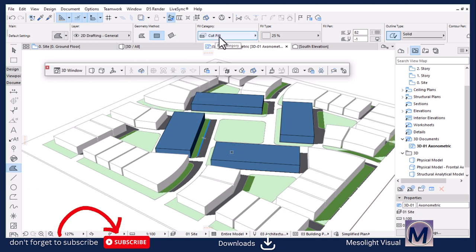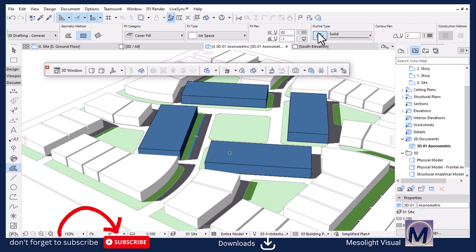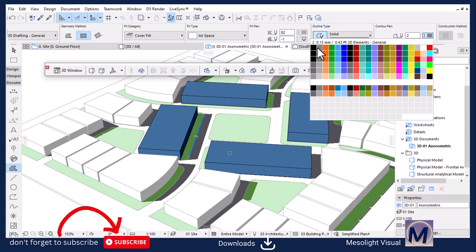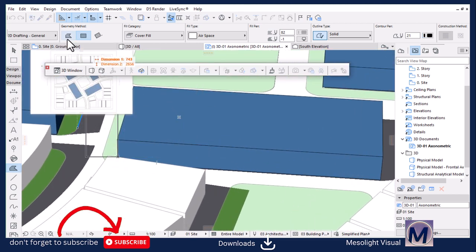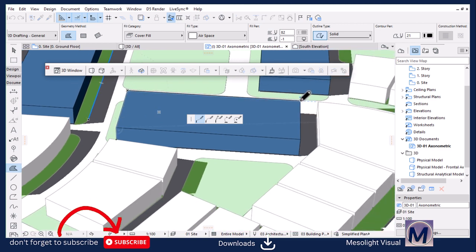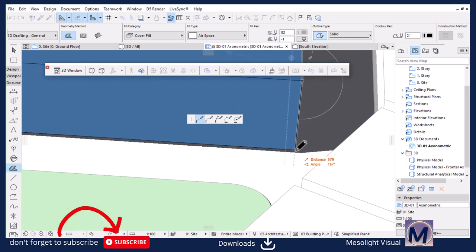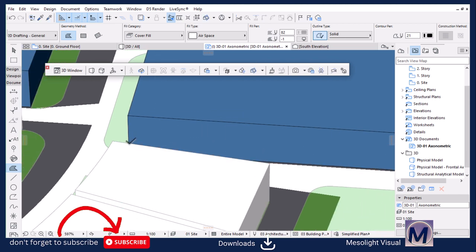Under fill tool, I'm going to change the fill category to a cover fill. Make it airspace, because we don't have to change the color. We just want the outline. So if you come here under the outline, make sure it's active, and then we're going to find a thick pen. I think 0.35 is fine. And then I'm going to trace over by using the geometry method of polygonal. Let's trace over the outline like that. There we go. Then click there.